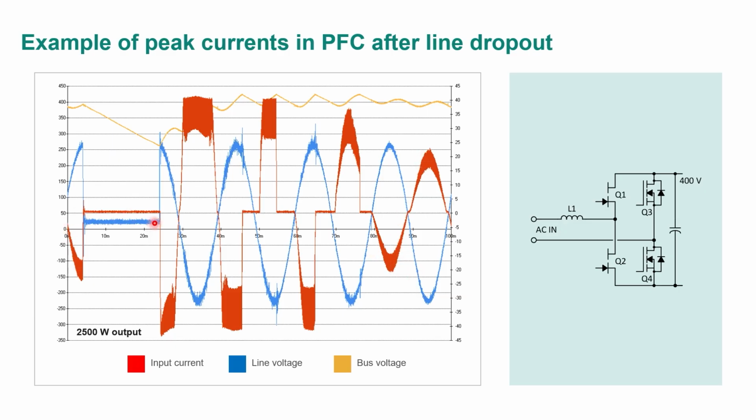Now, if I get a line cycle dropout, I have to recover from that. The circuit is at its absolute limit. It's hitting current limit every single cycle. And my peak current, now this is actually looking at the input current, not even the inductor current. The inductor current is probably going to be even greater than that. I have ripple current going on here.